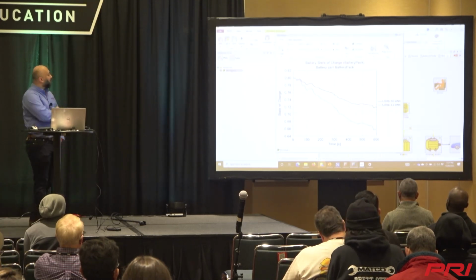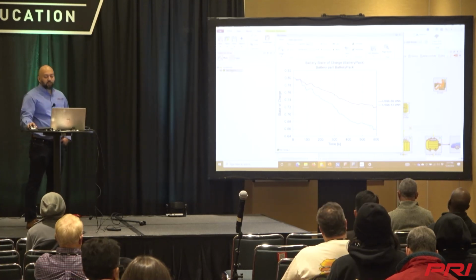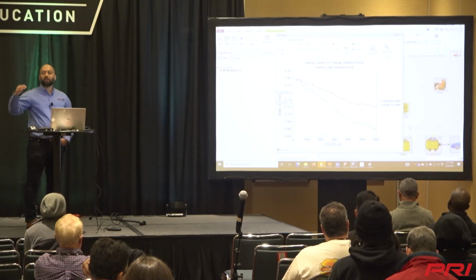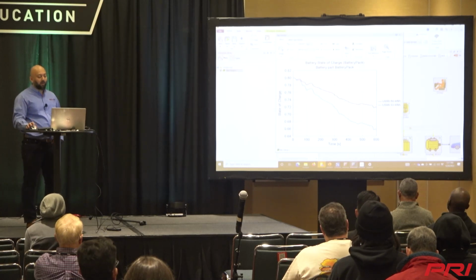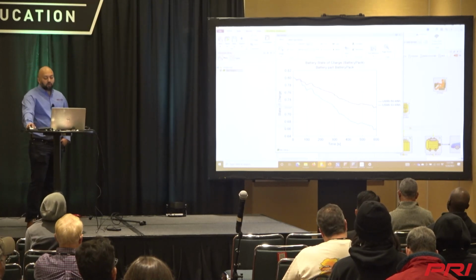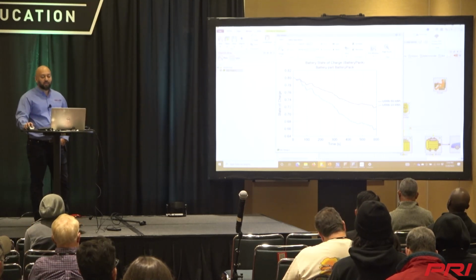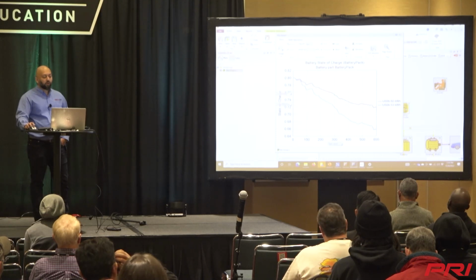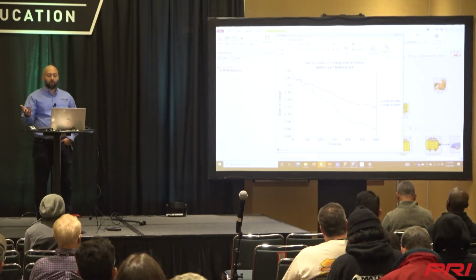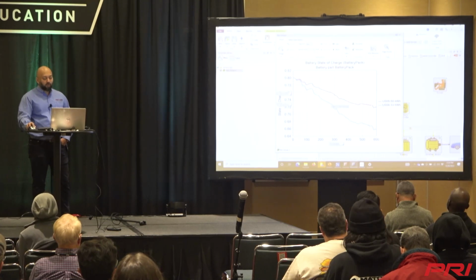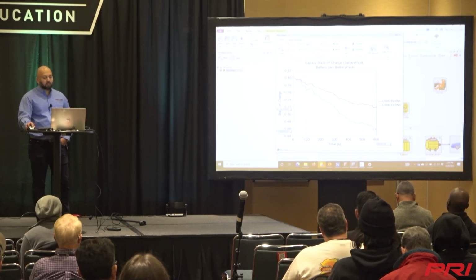So as you can see, on the x-axis you have time. That is the time to run that drive cycle. On the y-axis you have state of charge, or the percentage battery that you have remaining. So with the 50 kilowatt hour battery, it's obvious that you will have more charge remaining by the end of the drive cycle. So you're going from 0.8 to about 0.72. With the 33 kilowatt hour battery, which is a smaller one, you are using a lot more energy. So you are going from 0.8 all the way down to 0.65.